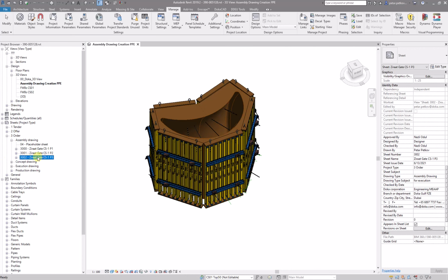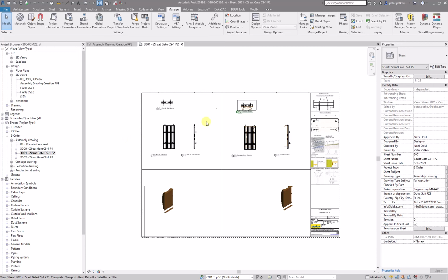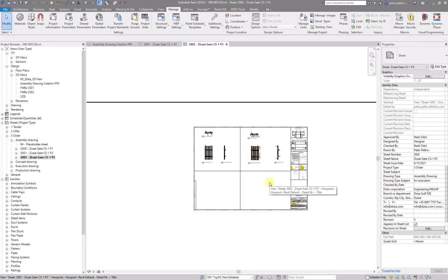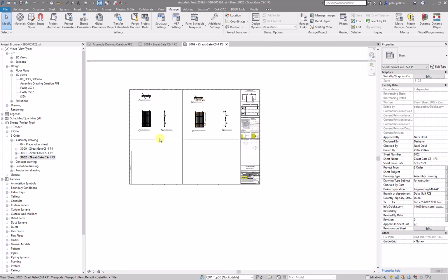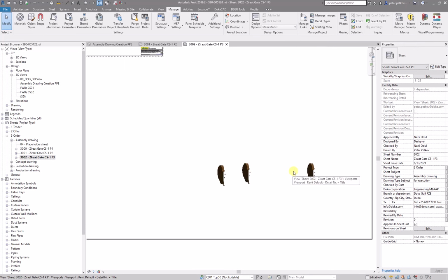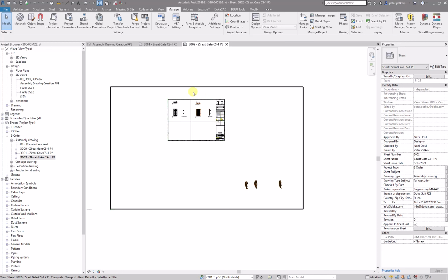So let's see the result, because this is what I showed you as a template, but I did some finishing touches on it. This is what the script creates automatically for you. So as you can see, it looks pretty much the same. The only thing is that you don't see the 3D views, and unfortunately the 3D views have their outlines or crop boxes spread too much around, and currently they're covering the entire drawing, so you cannot really touch anything on the drawing.